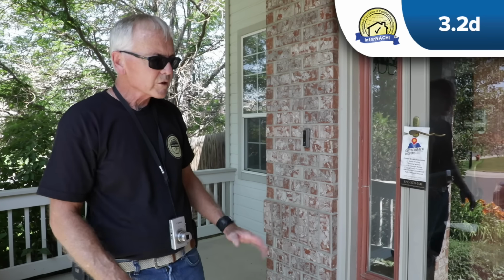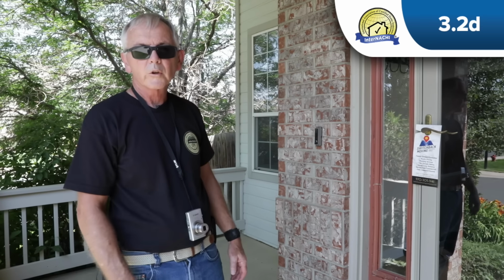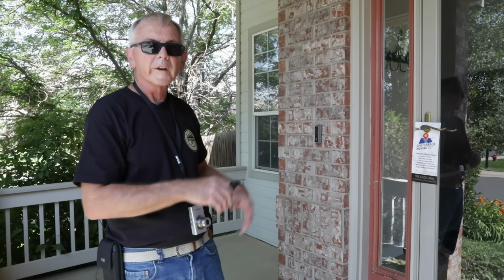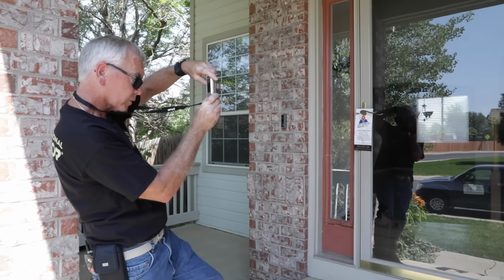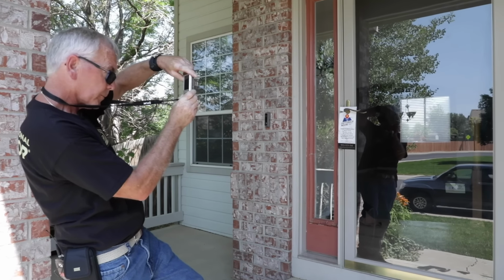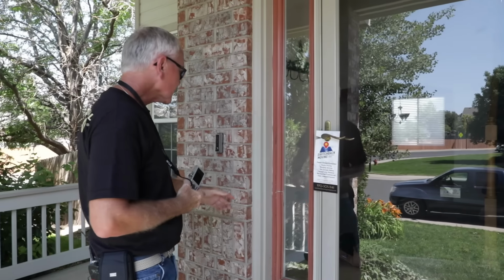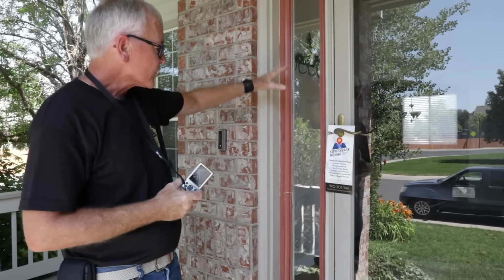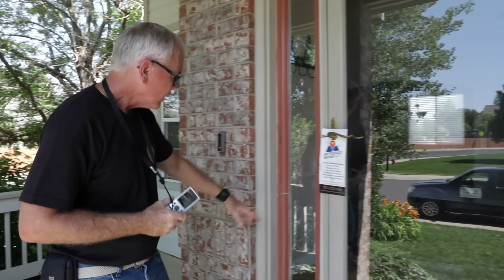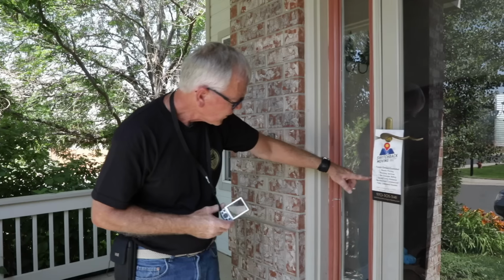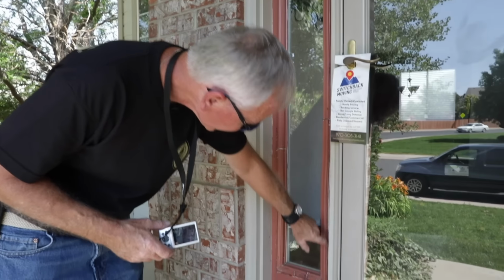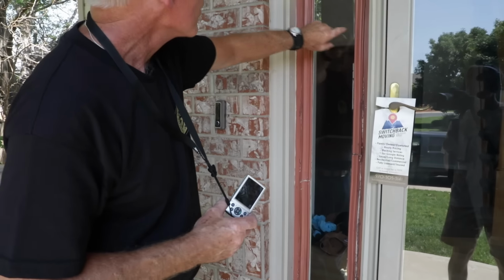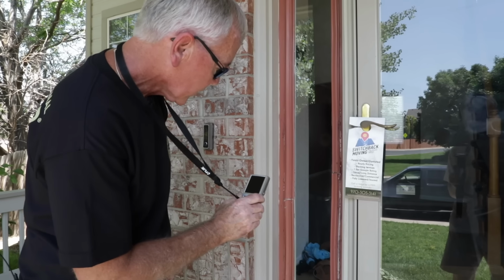Now the SOP tells us to inspect all exterior doors. So we're going to start with the front entry door here. I'm going to go ahead and take a picture just for reference. And right away I can see these side lights, which are on both sides of the entry door. We've got some broken trim around the glass. We've got a lot of failed caulking. They go up and down the sash.